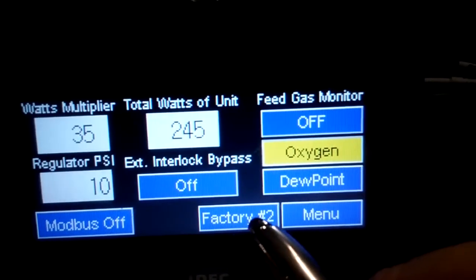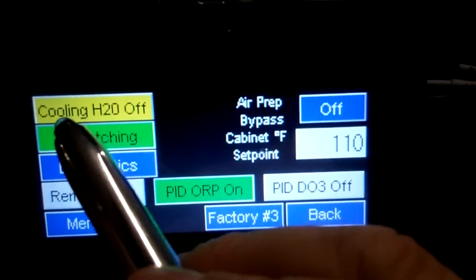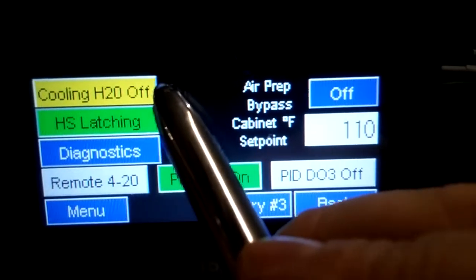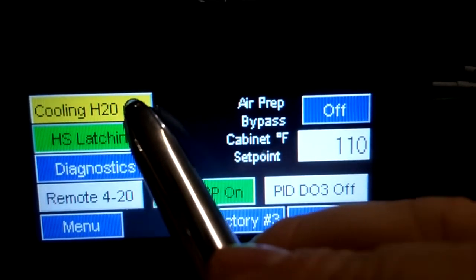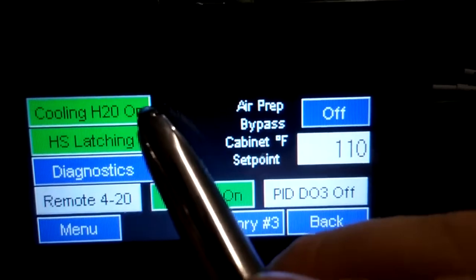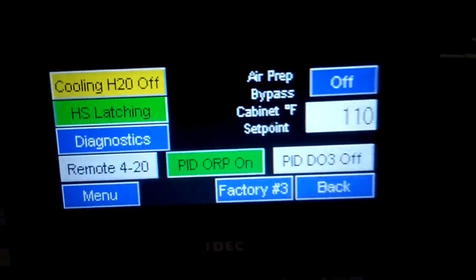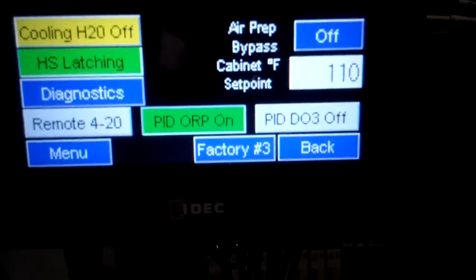Okay. We switch to the Factory 2 screen. Here we establish if the generator you're controlling has cooling water. If it's an air-cooled one like this one is, you would leave that turned off. If you activate it, that generator requires cooling water, and it will now populate an icon on the alarm list for cooling water fault or status.